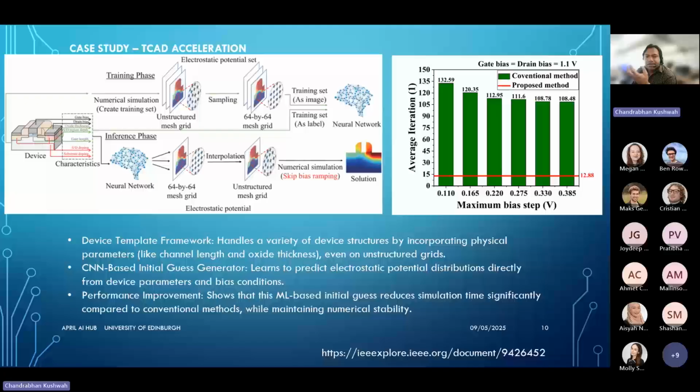So choosing appropriate sampling points is crucial because the device dimensions vary, particularly the gate length. Fixed sampling coordinates are impractical. Instead, sampling positions are defined as a function of gate length and position index. So, for example, in the horizontal direction the gate spans from the 44th point. In the vertical direction, the junctions of source and drain are located around the 36th point. So the sampling points are concentrated near the junctions to ensure the details.